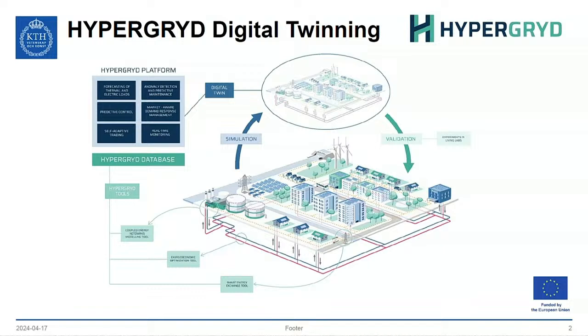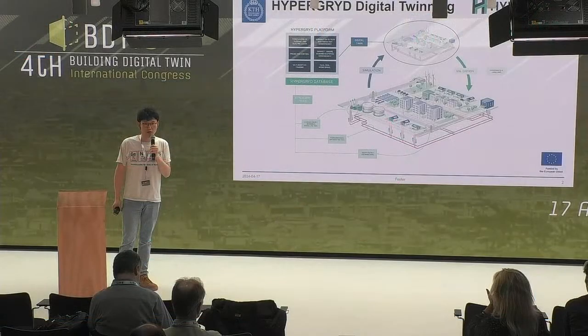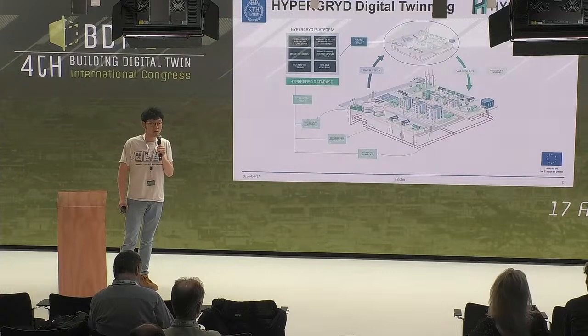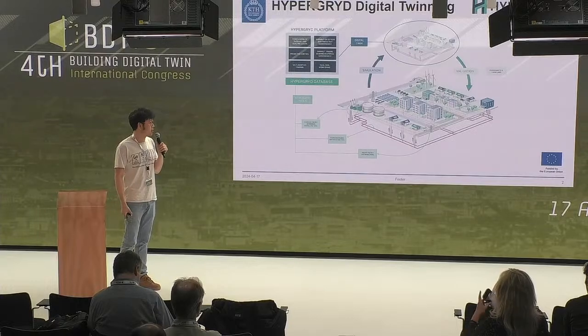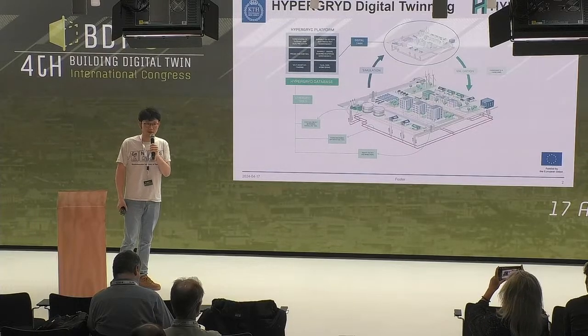And when it comes to energy system, we focus on, for example, beyond one single building to the district. It's very important for us to understand what's the purpose of having a digital twin. So digital twin should serve a purpose. And that's the whole motivation of this aspect of the project, how it's linked with digital twinning techniques. And this is not really much into, for example, how to design the district, but very much into the control and how to develop control sequences to optimize the operation of the energy complex in a district